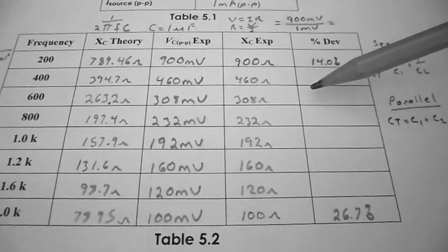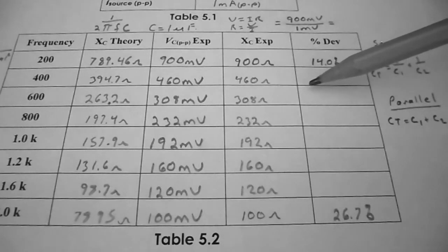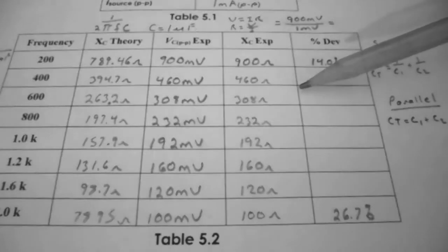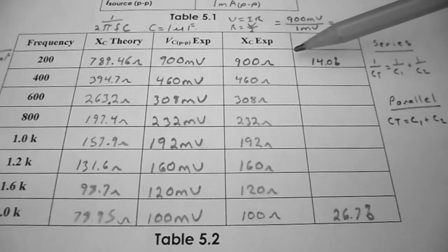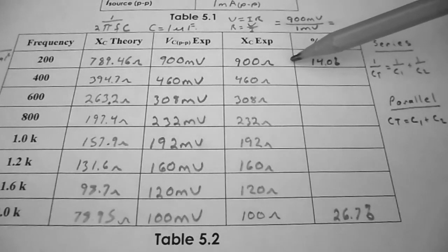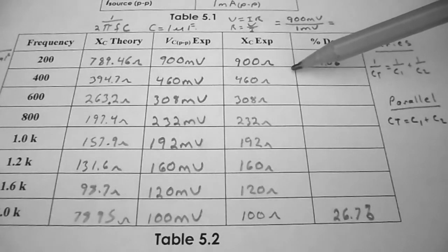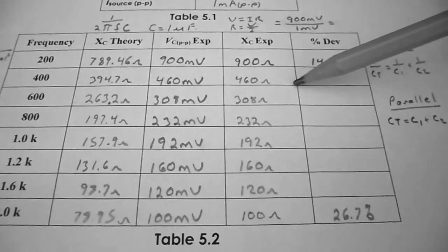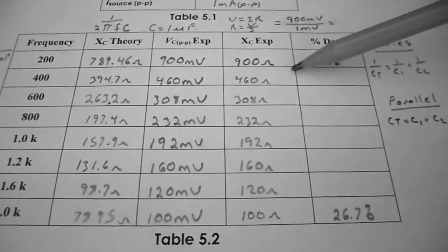You have to remember that capacitance, or a capacitor, is made up of two plates separated by some kind of insulator. So in our case, when we build a circuit on a trainer and we push a wire into a connector, the wires have actually oxidized or started to rust. Our connectors are fairly old. Those trainers are like 30, 40 years old, so their connections have oxidized a bit. So whenever you put a wire into a trainer, there's always a little bit of capacitance between the connection.